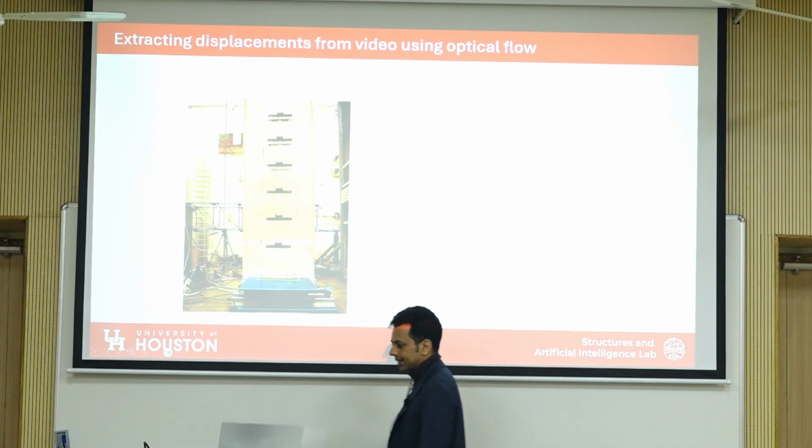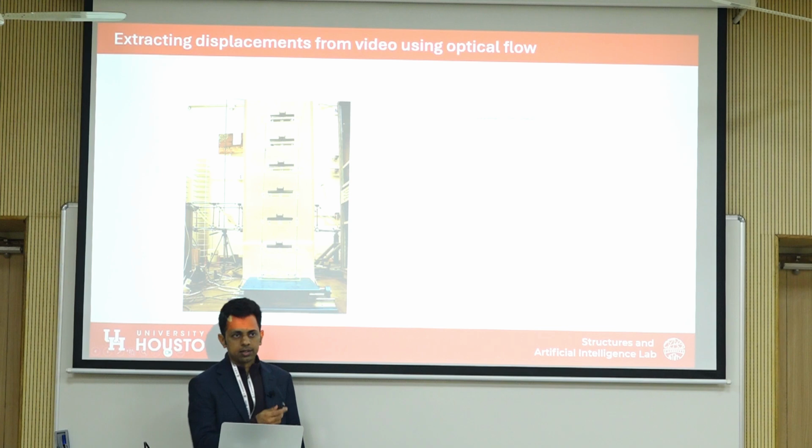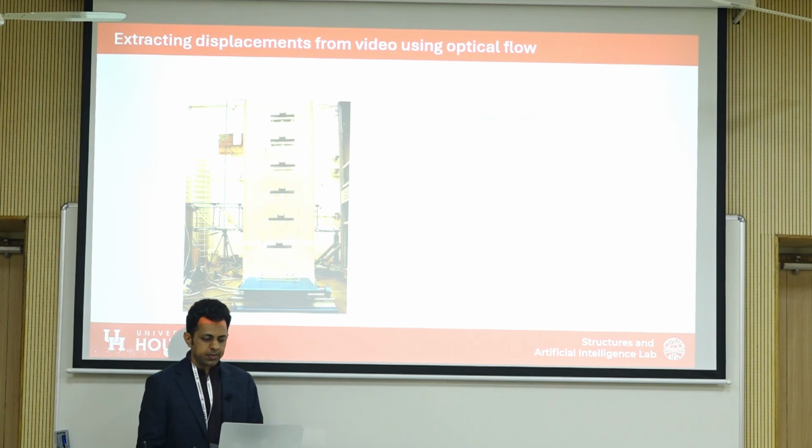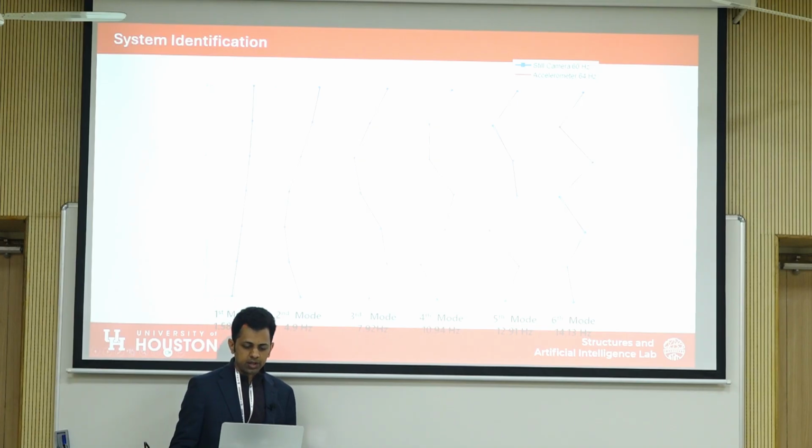We'll look in more detail about how you might do this, and you will get to experience it yourself. But once you've extracted these displacements, you can do all sorts of things that people have studied in structural health monitoring and modal analysis. For example, you can obtain the mode shapes. So this gives you valuable information about the dynamics of the structure.